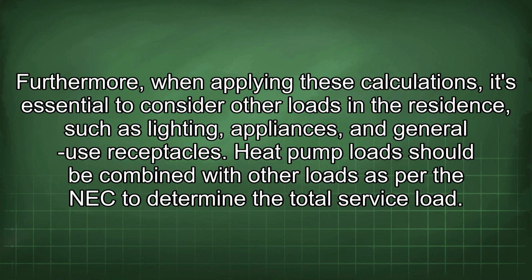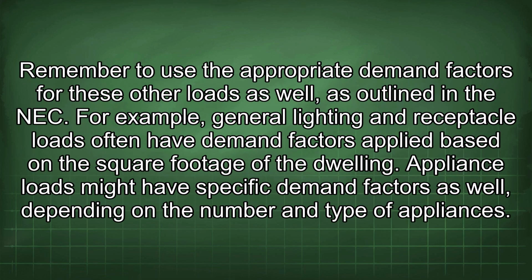Furthermore, when applying these calculations, it's essential to consider other loads in the residence, such as lighting, appliances, and general use receptacles. Heat pump load should be combined with other loads as per the NEC to determine the total service load. Remember to use the appropriate demand factors for these other loads as well, as outlined in the NEC.